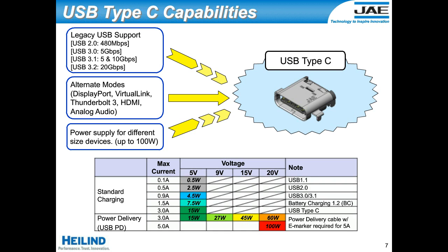However, over time, USB has started to become the industry standard for charging smaller devices, and so the power output through the USB connectors has started to go up over time through new revisions of the USB specification. With Type-C, it's now possible to quickly charge devices that have batteries, as well as devices that are not battery powered and have to be permanently plugged in to the wall outlets.